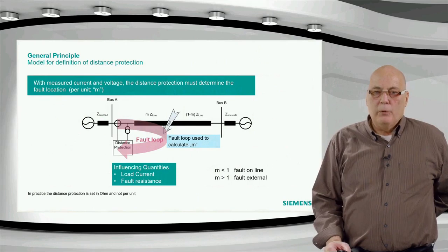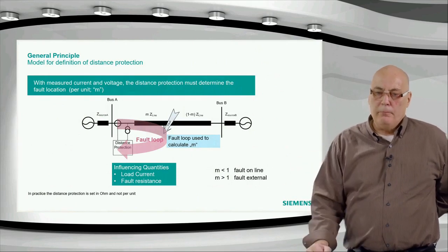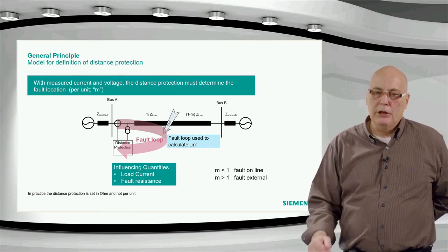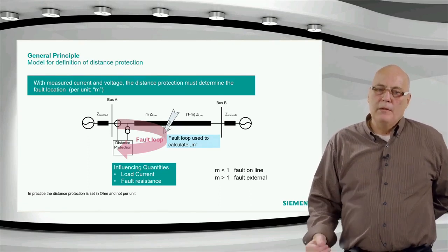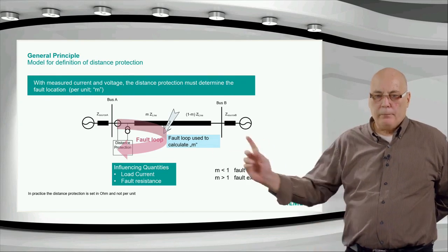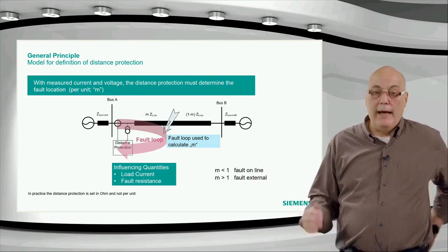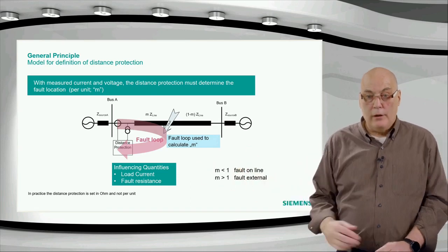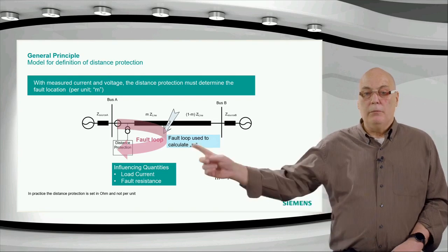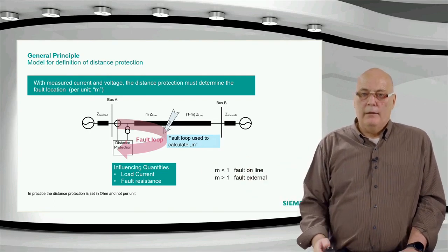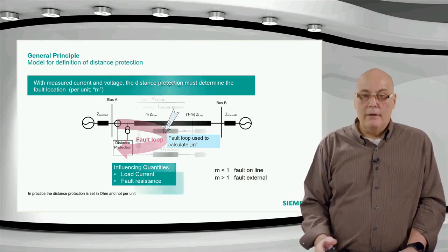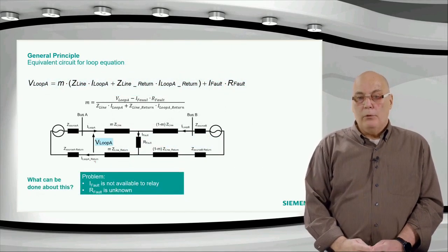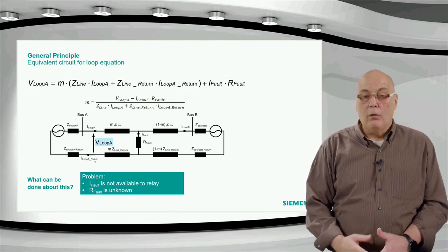All right, so we've gone through a few aspects explaining the distance protection, localization, how it's going to measure, some of the problems it will be facing. We've used this definition of MZL to localize the fault in the loop equation. We've seen that the load current can affect the measurement via the fault resistance, and ultimately that is the explanation of distance protection. So if we come to this situation now to see how are we going to deal with